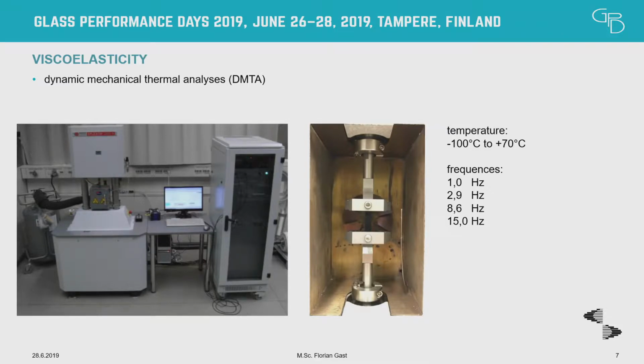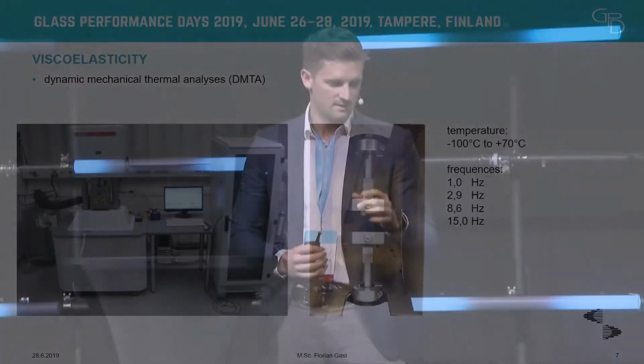What you do is you have different frequencies as impact, and you have these frequencies at different temperature stages. So starting at plus 70 degrees, going down to minus 100, and then you can tell how the material's behavior is at different temperatures and also different frequencies.